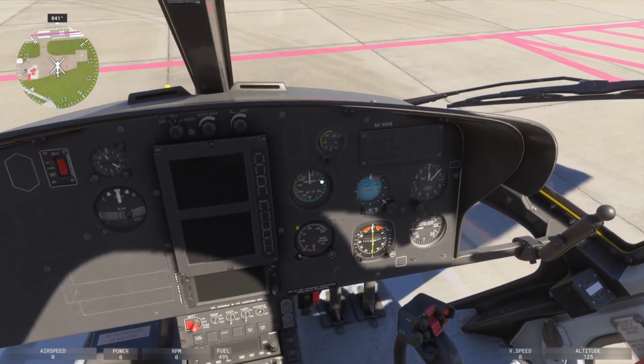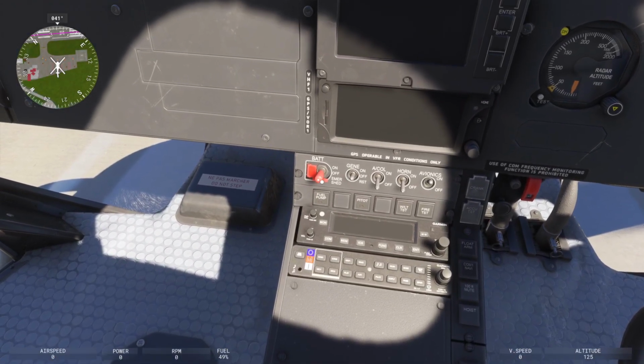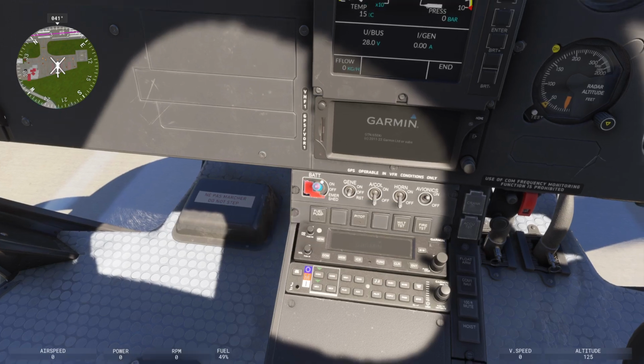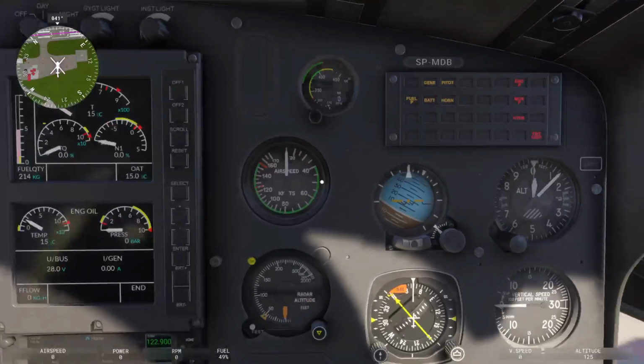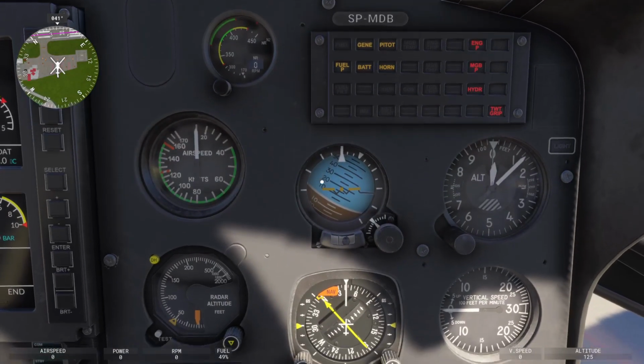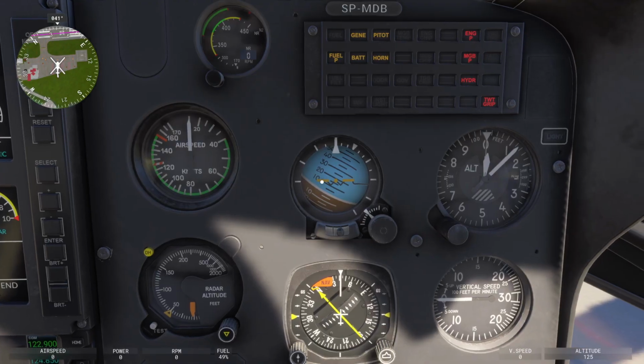So we're going to very, very quickly start this aircraft up. For that we're going to have the battery turned on. This applies DC power to the aircraft. One of the things I don't like about this is if you have a look now, my attitude indicator is beginning to come alive. Or is it not? Well, it might be different on this.